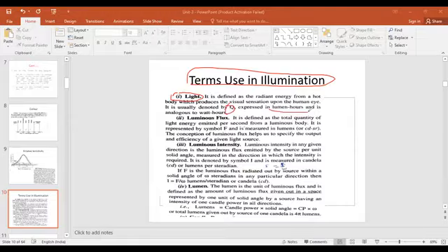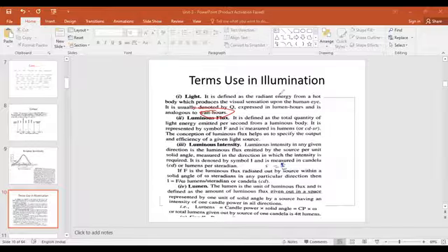And what is the unit? Lumen-hour, that was discussed in previous class. Lumen is the output of a lamp. Okay, it is a unit of luminous flux. We will see luminous flux also. So lumen-hour is analogous to watt-hour. Watt-hour is the unit of what? Unit of energy. So light is equivalent to that lumen-hour. In electrical terms we say watt-hour, power and time. So that is energy. Then luminous flux.